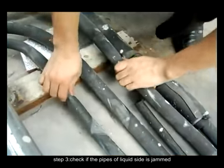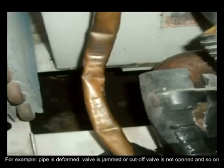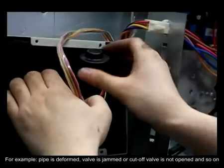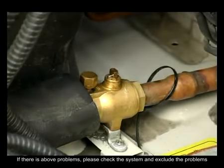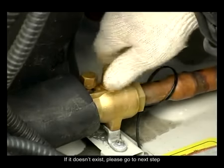Step 3. Check if the pipes of the liquid side are jammed. For example, a pipe is deformed, a valve is jammed, or the cutoff valve is not opened, and so on. If there are the above problems, please check the system and exclude them. If they don't exist, please go to the next step.